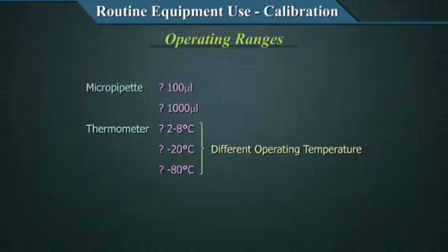The thermometer may be able to measure up to 100 degrees or 60 or 70 or whatever, but it's not relevant for you. Your fridge thermometer has to measure and be very sure of the uncertainty between 2 to 8 degrees. Similarly, for a water bath, your 37 degrees centigrade is important. So that is how you decide what your operational requirements are and what the uncertainty is there.